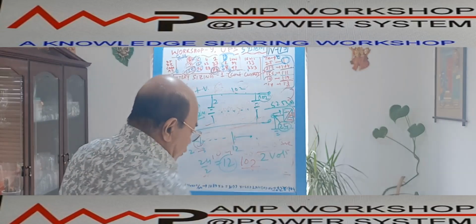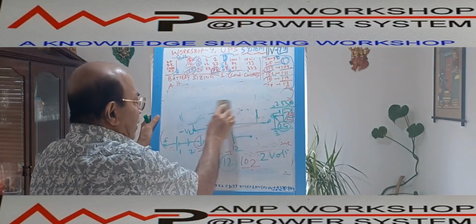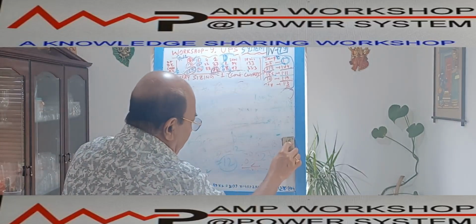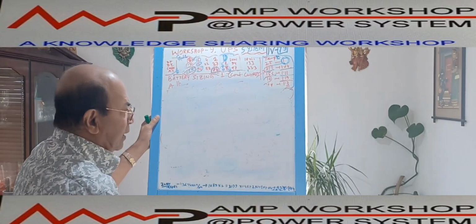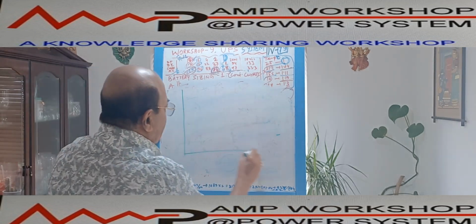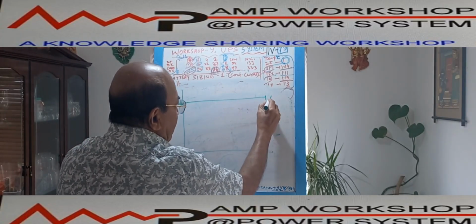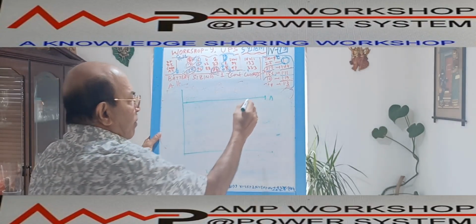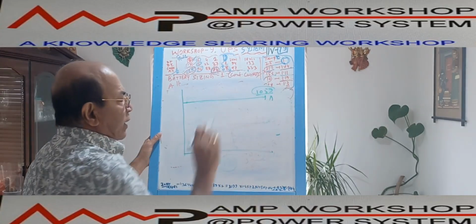My output load 20 kilowatt is a constant. This constant power is not getting changed over time. But suppose this power in kilowatt is not constant, it is changing. If we see the current profile in this case, how is that? The current is constant over the 2 hours. This current is constant. How much current is it? It is approximately 1059 ampere. That is a constant current.